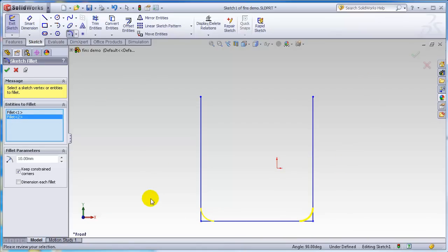Let's see what I think about the size of them. That's maybe a little bit on the large side, so let's go with 7 millimeters of fillet. I'll change that size, and I'll click on check. And now I have only one size indicator because this one is set to be the same size. And so my geometry is about right. There's some things about it that I don't like right now, but I think I will fix it later when it becomes important to fix it later.